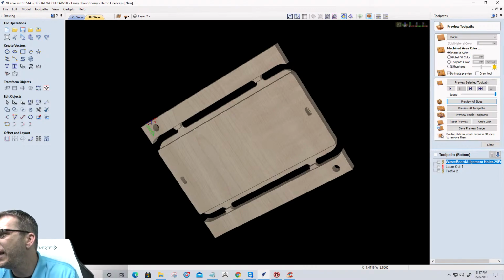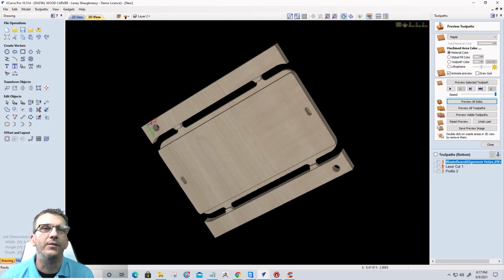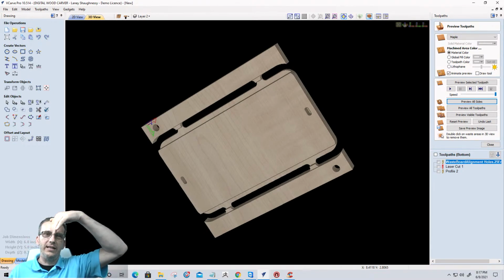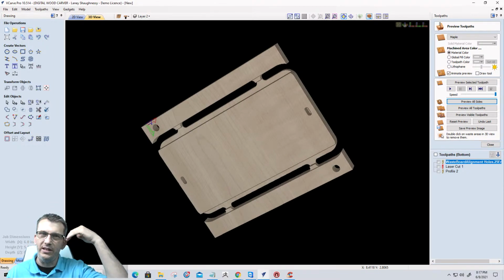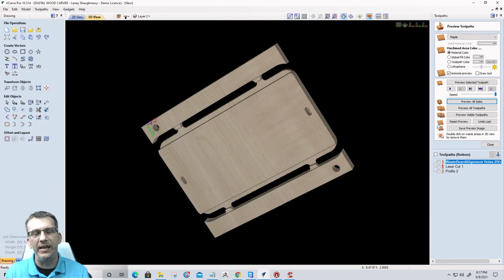Why not finish the edge with a dovetail bit so the lid slides underneath? Jonathan, you could do a sliding dovetail. Like I said, this is a straight sliding lid box. And if you're going to use a dovetail bit in your CNC, you would set that up as a dummy toolpath using a dummy bit like an end mill, because we can't draw a dovetail bit in the Vectric software.